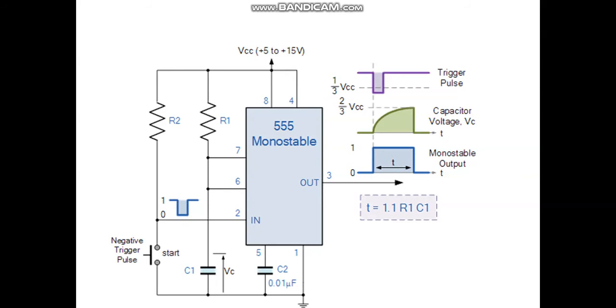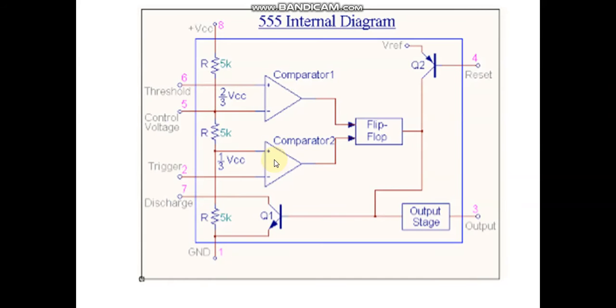This action in turn turns off the discharge transistor connected to pin number 7. So we had seen the discharging transistor Q1. When this is at high, this point is 0, and automatically Q1 turns off, thereby removing the short circuit across the external timing capacitor. So when it is off, this point is not shorted. If this is on, the R does not come into account. This becomes another part, that is, you are bifurcating this R.